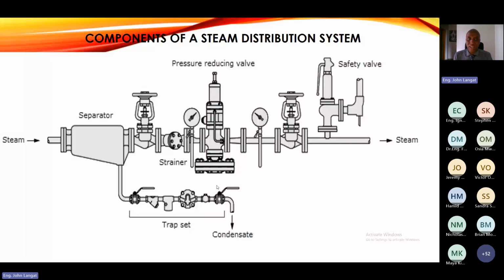The length can vary. And also one more thing is that an effective steam system should always have these separators at several places. It's not only one. Normally this separator is put just before the plant. Say if you have a dryer, you just put it just before the plant. If you have an autoclave, you just put it there so that water doesn't go into the plant, or the radiator for that matter.